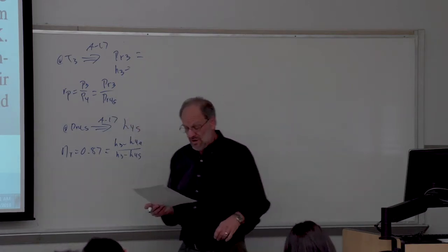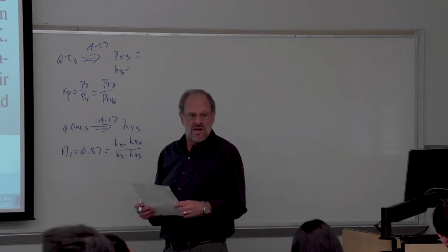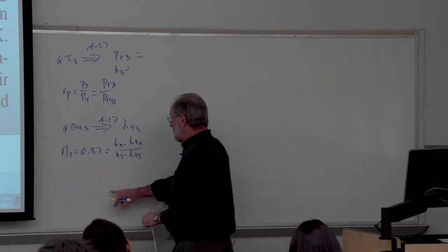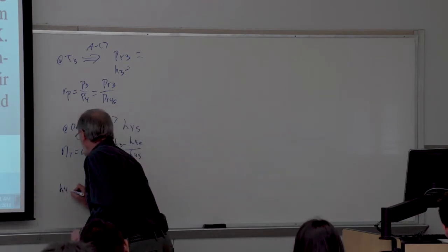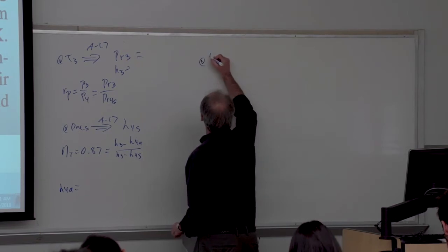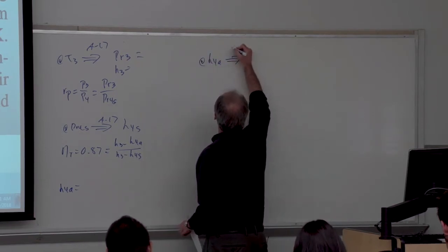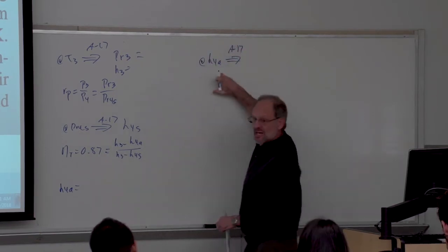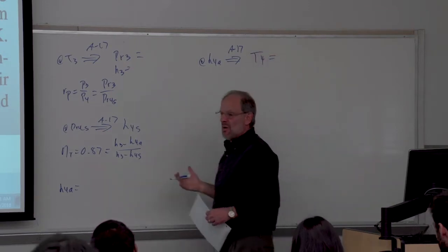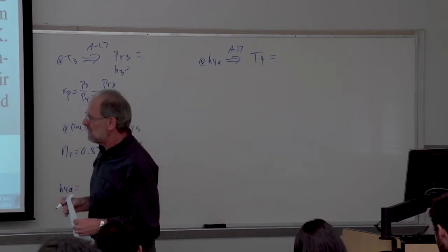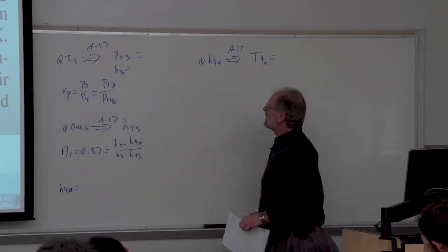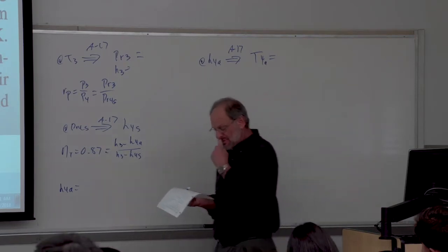And frankly, once we have all these enthalpy terms, then it's just a matter of finding all the other data we need. So for instance, once we've found H4 actual, which again we'll look up in a minute, then we're going to go back into table A17 at this actual enthalpy, and this will allow me to find T4. Now, T4 is the actual temperature at 4, right? T4A, so just as a reminder, don't forget your little A there. So this gives me that temperature.